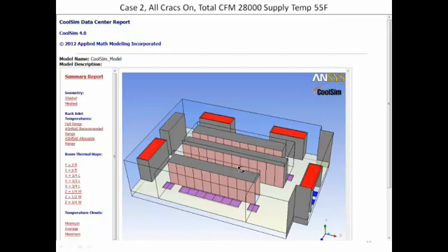Now the way I was able to tell that is that, again, they had taken a anemometer and made measurements on the floor tiles, and they weren't matching the factory specs on the floors. Just way too much pressure. So again, I backed them off to 7,000 each to match what they were measuring in that room, and it was because too much pressure caused by way too much airflow.